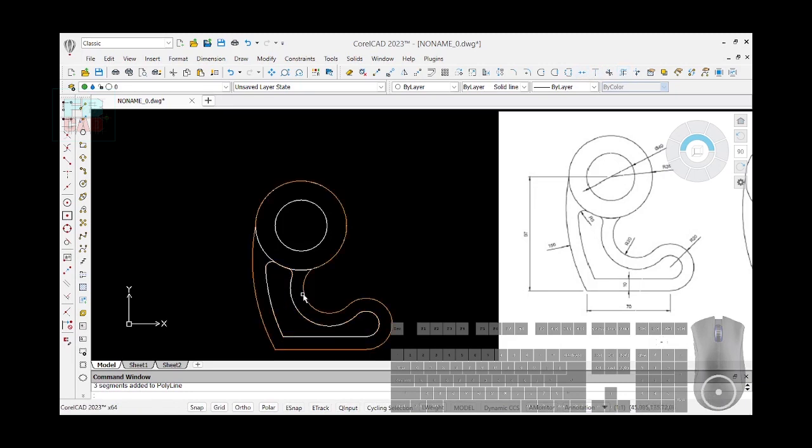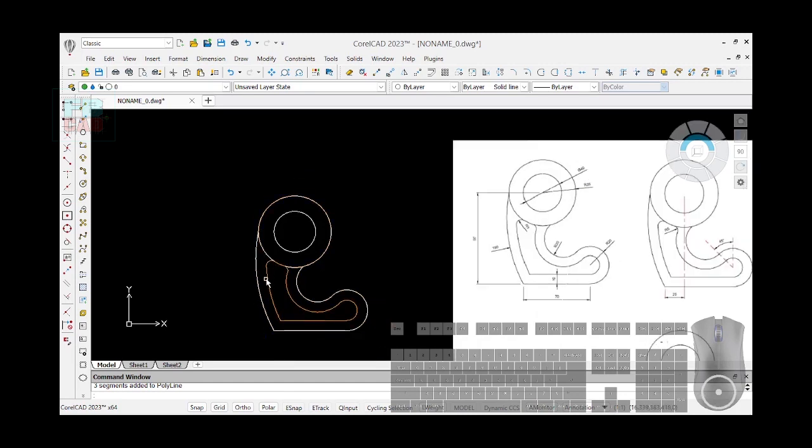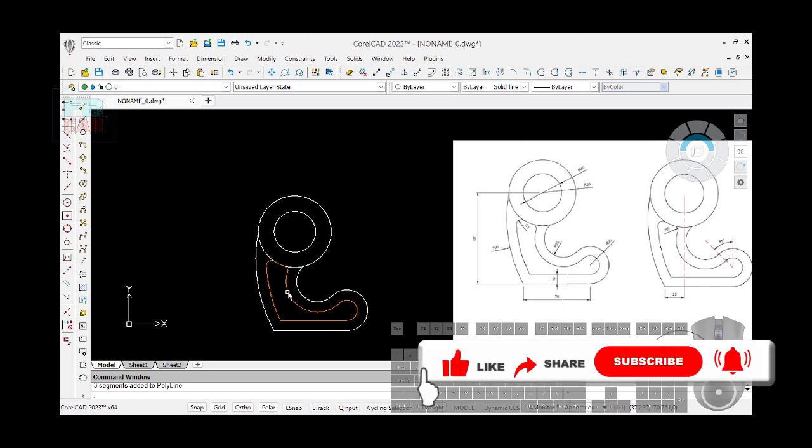You can see it's joined. This one is joined. We have this one, we have this one. Now the joining is going to help when we start working on 3D. For you to have a closed shape, all your shape needs to be joined together. Otherwise, it's going to be a kind of panel whereby you have an open box or a panel drawing. So that's the purpose of joining. We've not been doing that, but we'll be doing that subsequently because we're going to be revisiting all of these exercises and transform almost, if not all of them, to 3D.